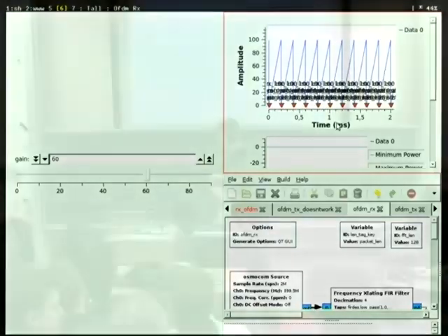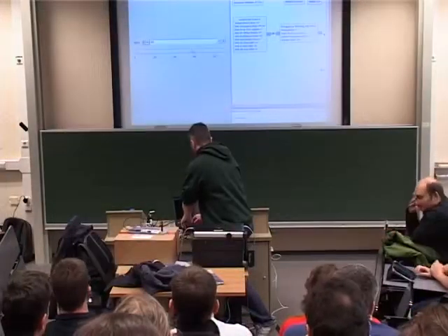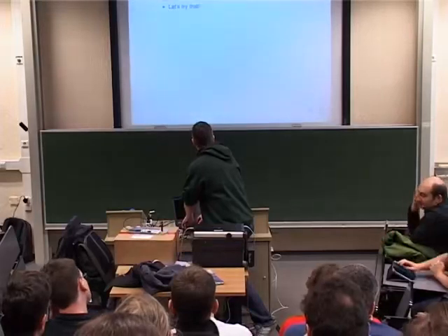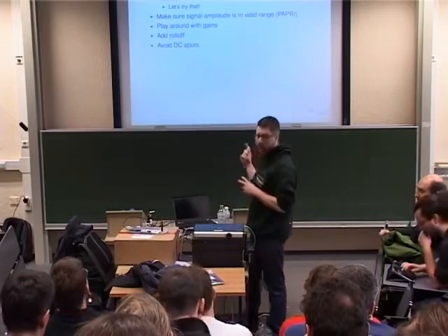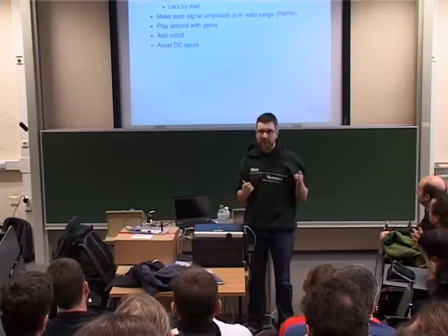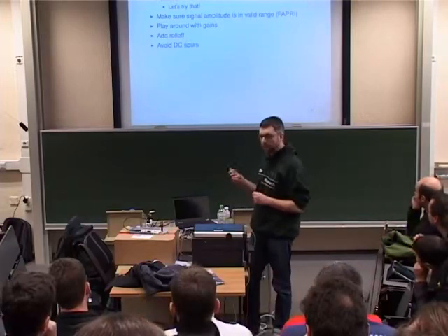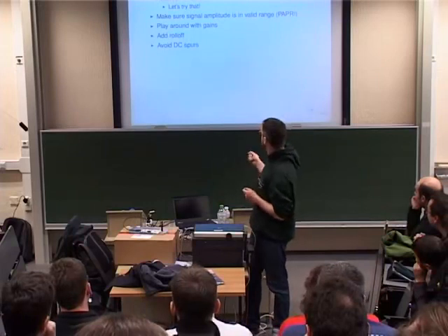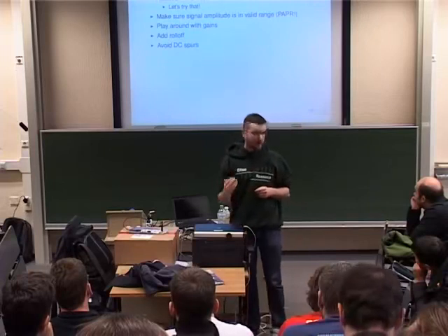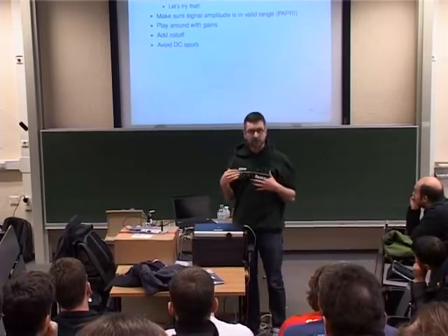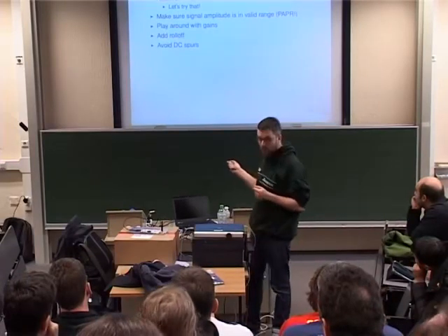Fantastic. So first step, make sure you actually get a nice spectrum at the receiver, and you'll be fine. A couple of hints. OFDM has this problem that we call the peak to average power ratio, which is why we get this clipping. With other modulations, it's not quite as difficult. Play around with the gains on both the transceiver sides, and in doubt, go back with the gain. Actually, reduce gain on both sides. It'll also help with your linearity. There's a feature called roll-off.